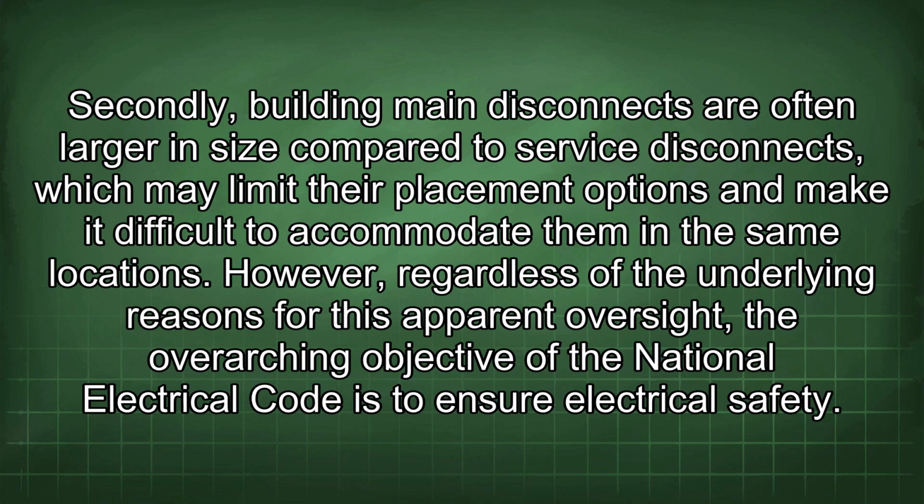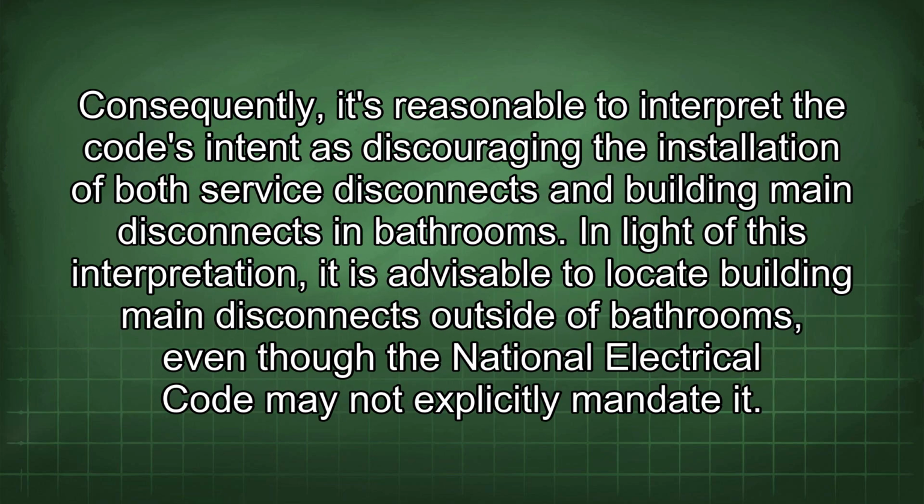However, regardless of the underlying reasons for this apparent oversight, the overarching objective of the National Electrical Code is to ensure electrical safety. Consequently, it's reasonable to interpret the code's intent as discouraging the installation of both service disconnects and building main disconnects in bathrooms. In light of this interpretation, it is advisable to locate building main disconnects outside of bathrooms, even though the National Electrical Code may not explicitly mandate it.